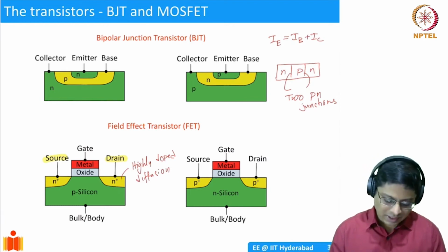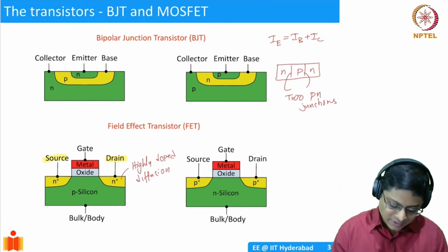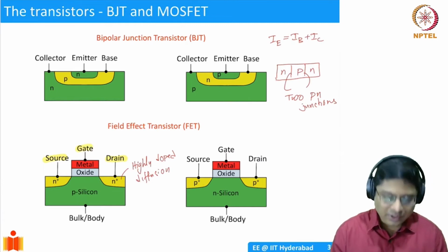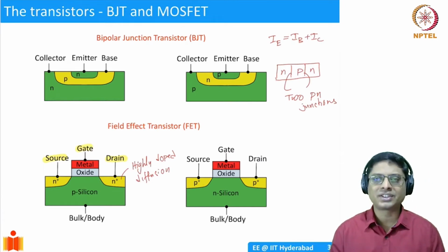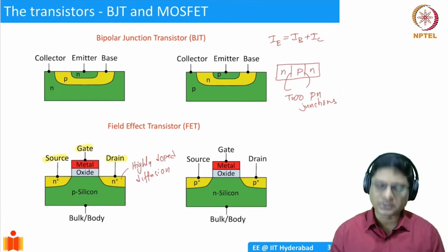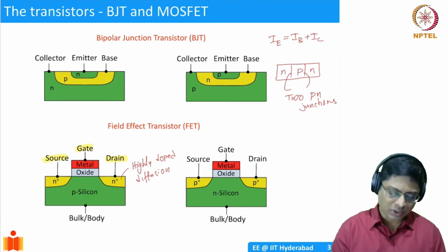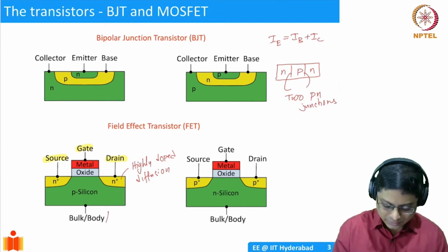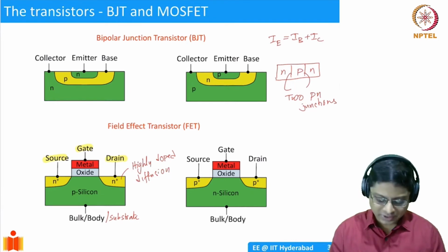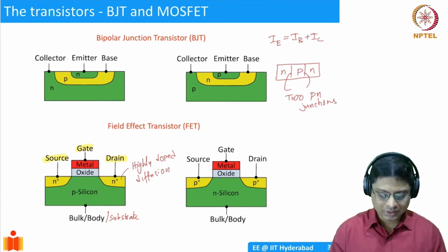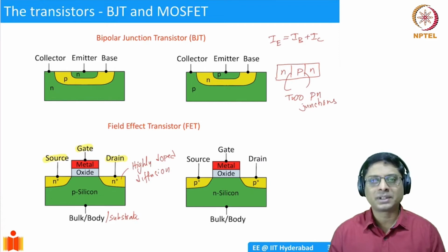All right, and then the gate we have already seen, and we will also introduce another terminal now, which in the MOS capacitor discussion we didn't mention specifically. We just called it substrate. Now you could call it bulk or body or even substrate. Typically people don't use substrate because we use S for source, and if you put substrate, that also becomes S and it's confusing.